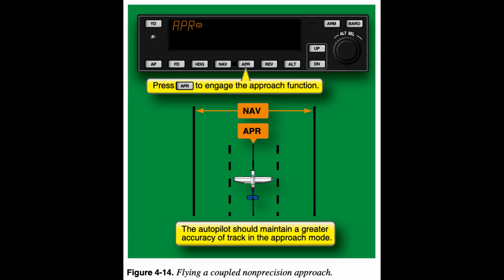Note, usually, this mode is not used with most GPS receivers. The GPS approach RNP, required navigation performance, of 0.3 induces the necessary flight tracking precision. This mode is used only if specifically stated as a command in the Avionics Handbook for that equipment in that aircraft. Like the navigation function, the approach mode can be used to execute precision and non-precision approaches that rely on types of ground-based navigation facilities, e.g., VOR, VOR/DME, and localizer approaches.